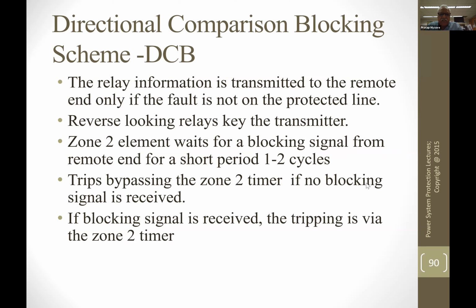The question that is asked is, do we have uninterrupted power supplies to energize the communication devices? No, we have a battery at a substation, right? That is the DC, and it has a charger, and it is supposed to be maintained. That is the one giving the DC. Most of the time it is just like an uninterrupted power supply. The DC is always on.